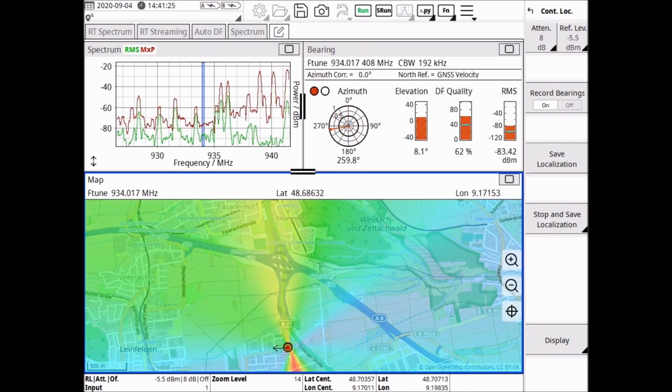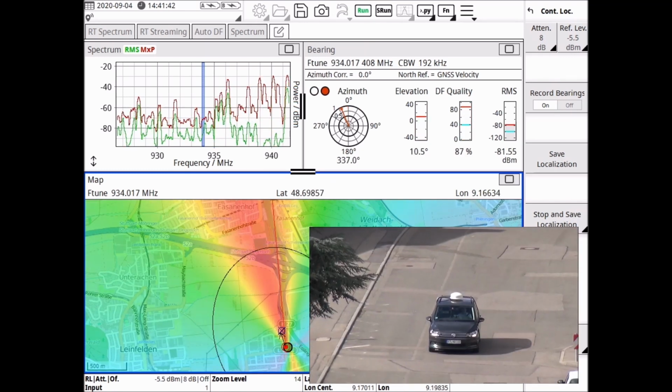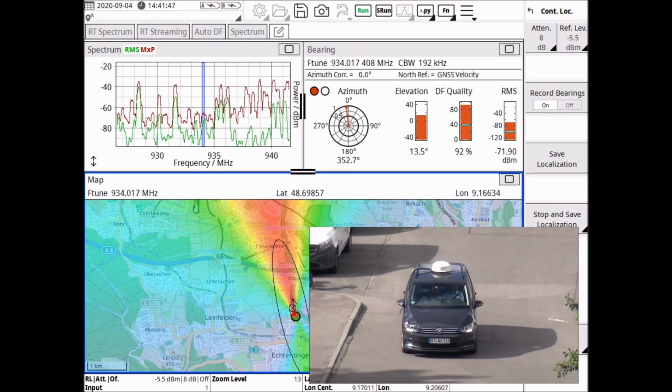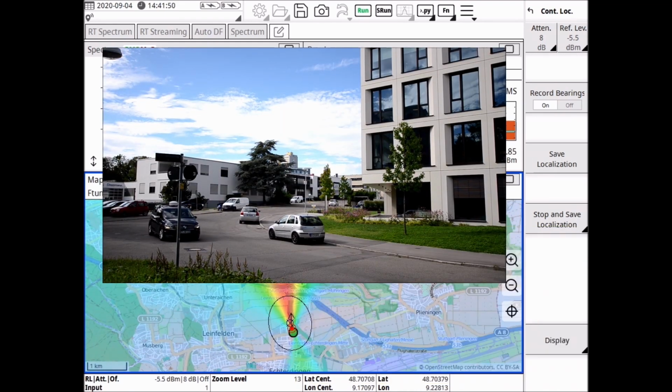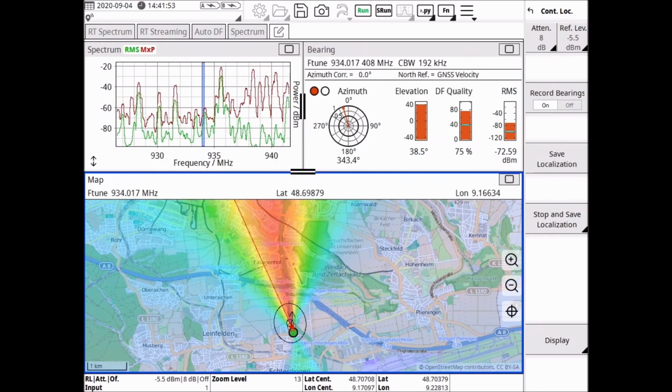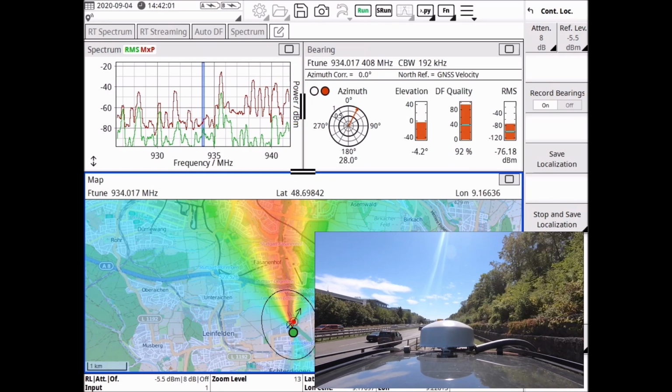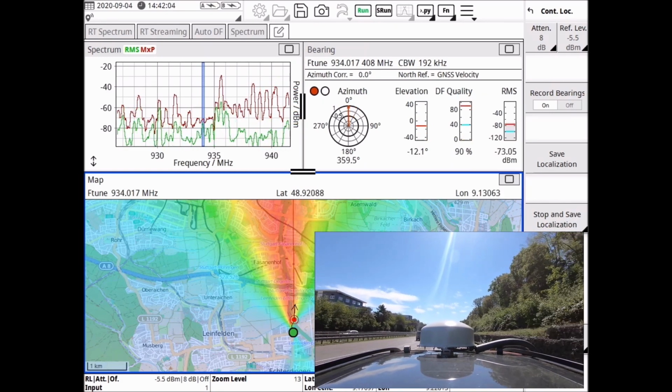The stronger the signal becomes and the more line of sight events can be received, the better are the chances for quickly narrowing the interferer down on the heat map. Also, the driving route plays a significant role to reach soon success. The route should never be just straight, but it should make curves or even circles around the suspected area. By that, the SignalShark's 3-dimensional geolocation algorithm will be provided with even more useful bearing data.